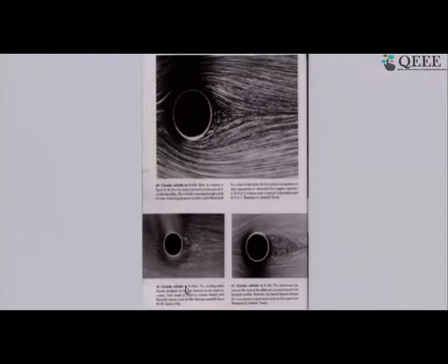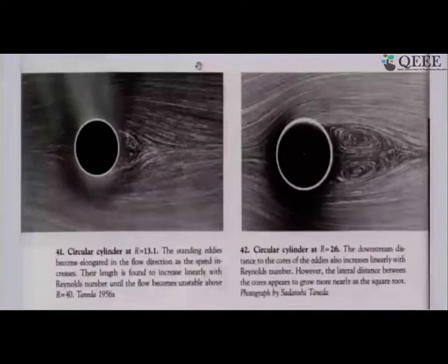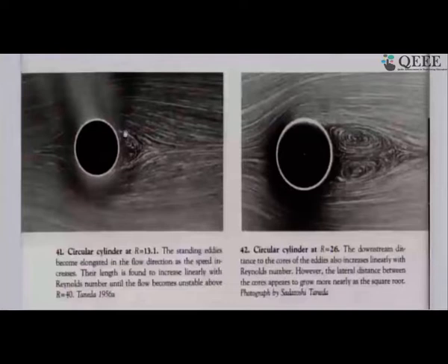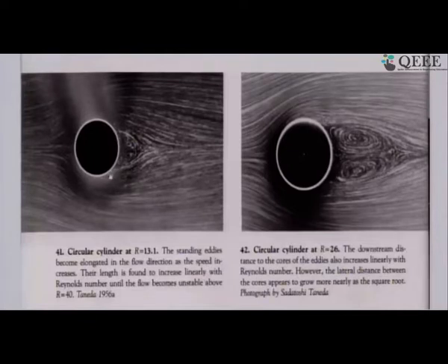Okay, then we look at this picture at the bottom over here. So here we have two pictures. This is at Reynolds number 13, and between 10 and 13 something has happened. Now what you see here is that the flow is coming here and going off that way. But here you see something else, which is that whatever fluid was there is moving around like this. Some fluid from the outside comes in, some fluid from this goes out, and this is a recirculation region. So two things have happened. You can see this line over here, and the same thing is happening on the bottom also.